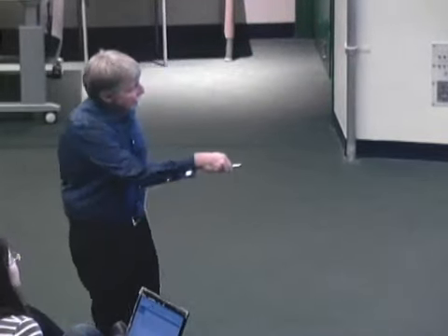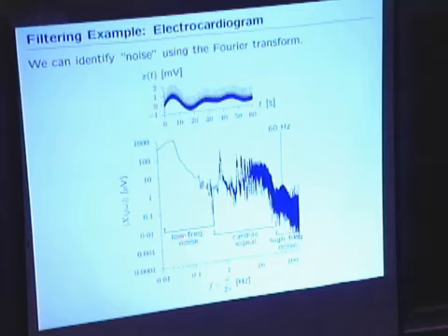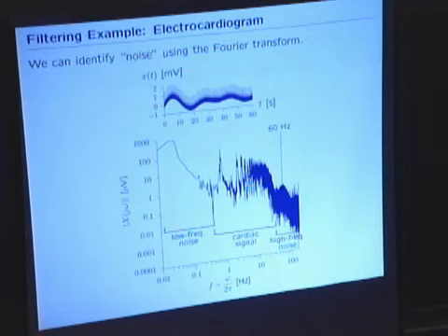Things significantly lower than a hertz probably aren't coming from the heart. Things that are up in the 10 kilohertz region probably are not from the heart. This enormous spike, what's that? That's the lights. That's the power. We distribute electrical power by modulating it at 60 hertz because that distributes better, but then it radiates. And so some of that can be coupled into everything, including me. So the big line is the 60 hertz that's being coupled from the power distribution network into the person whose